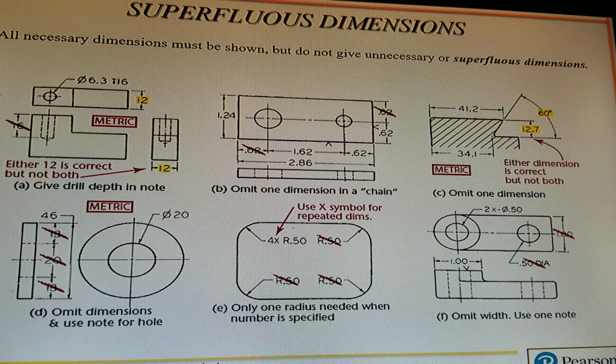Plus, it has something to do with tolerancing. Your tolerancing usually applies the same as the overall dimension to two of the smaller dimensions, and if you start adding those up, you can mess up your tolerancing too. So be careful about that.